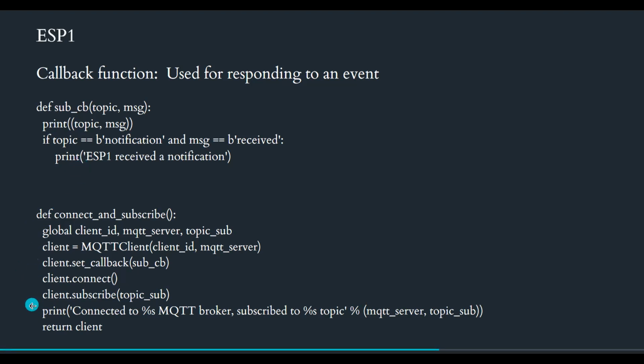So in this function, we are setting up what is the MQTT server and what is the client, and then we are making the connection between the MQTT server and the client. And then we are also defining what is the topic to which the client has subscribed using the client.subscribe function, right? So likewise, we can run this code to connect our client device to the MQTT broker.